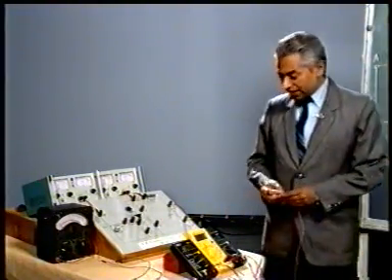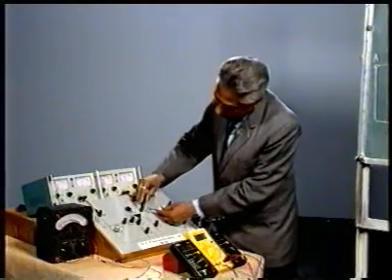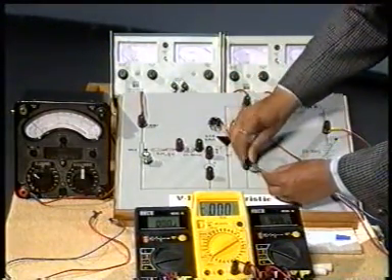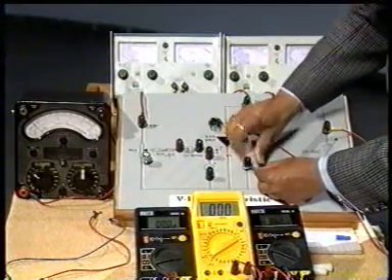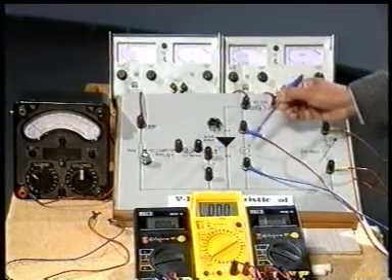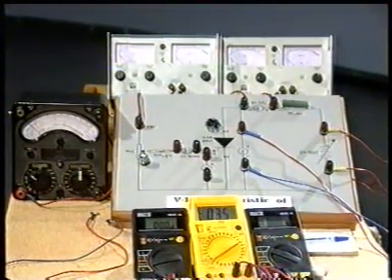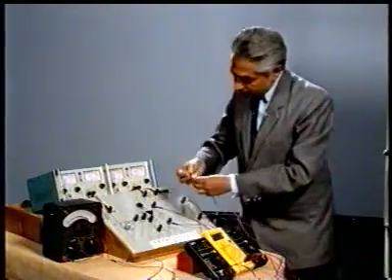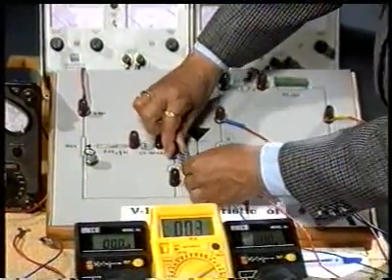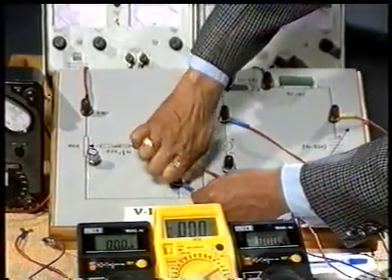So, this is the multimeter which will be connected across anode and cathode. This will go at the positive terminal, the red one. This will go at the negative terminal. So, this multimeter is going to show you the anode cathode voltage. Now, the yellow one, the middle one, I am going to connect for the gate voltage. The red one will go at the positive terminal, the blue one will go at the negative terminal, and